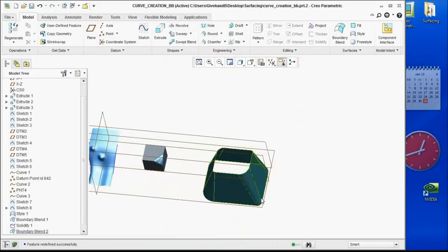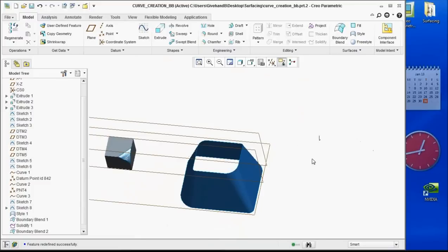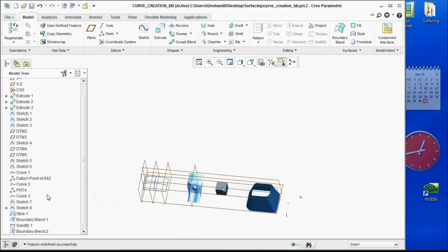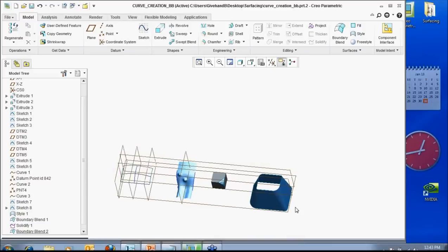I don't have an example of this, but if everybody can imagine a curve like this with a whole bunch of breakpoints and a straight line at the bottom, you could essentially drive all of this curvature into a corner if you wanted to. So all I have to do is have breakpoints up here, and in this straight curve that I have on the bottom right here, you can actually drive curvature to individual datum points if you want to, or you could break that curve however many times for surface patches to match. You actually can drive curvature from natural breakpoints in the curve to datum points also, if you've never accomplished that, okay? So a few different things you can do.